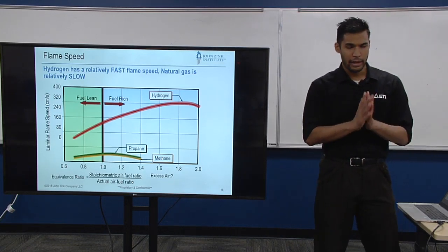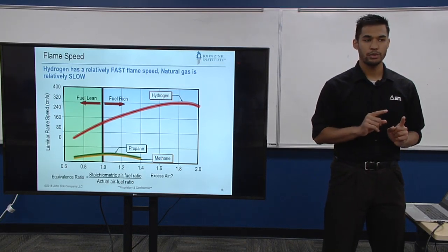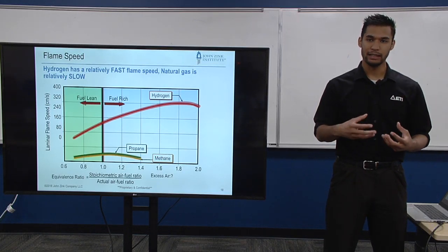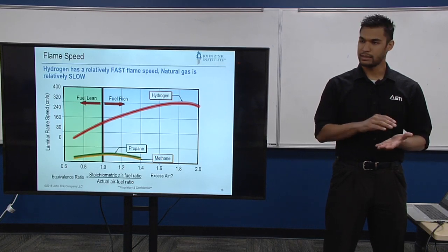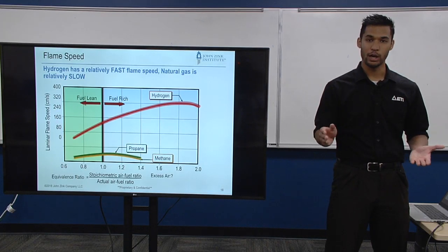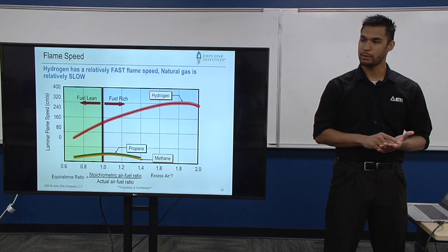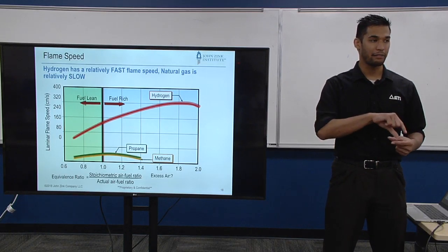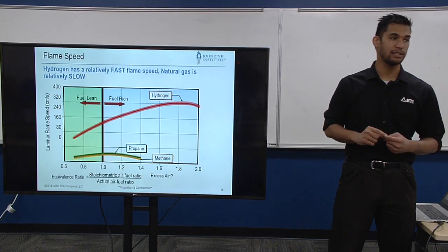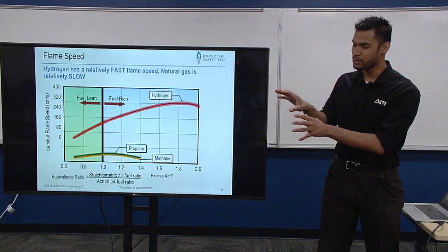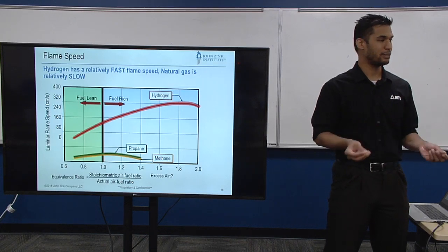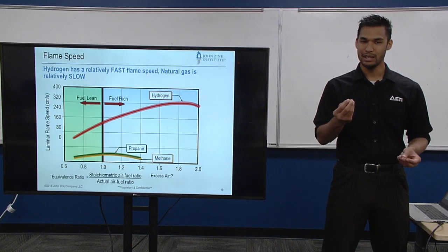Now, there's a very important distinction that we'll go into more next class. Laminar flame speed: if I have a laminar mixture of fuel and air, its Reynolds number is very low. How fast is it going to be propagating back? Because when you start adding high pressure situations, or high velocity flows where you're turbulent on the inside of the pipe, the laminar flame speed does not correlate to the turbulent flame speed in a way that's very intuitive.